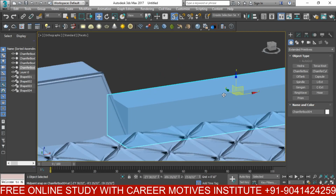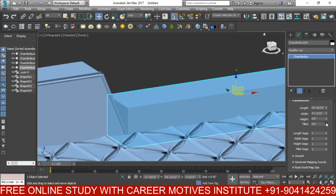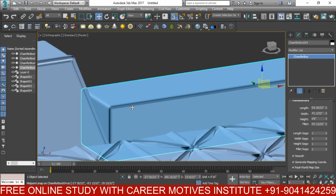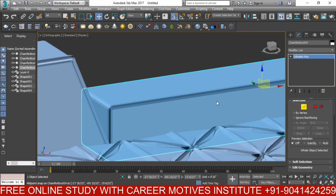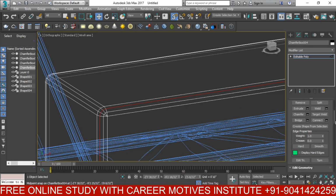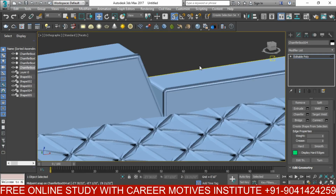Okay, again I'm going to modify it, I'm increasing the fillet value, and then right click, convert to editable poly, and then I'm selecting edge, F3, I'm selecting one line, then loop, and the same step create shape from selection. Okay, and then here we go.